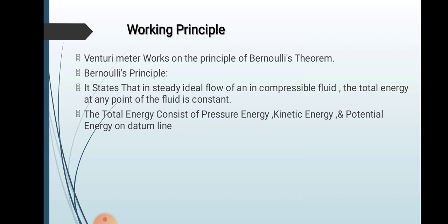Second, the tube can be used for high flow rates. Venturi tube is used for high flow rates, whereas orifice plate is only used for low flow rates. Third, the tube is suitable for fluid having suspended particles. These are the improvements over orifice plate. So nowadays a venturi tube is mostly used in industry for flow measurement of gases, liquids, etc.